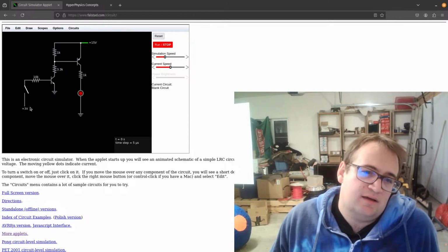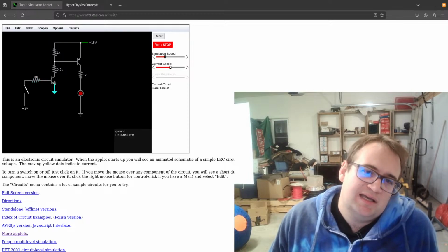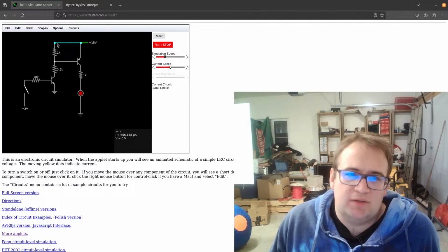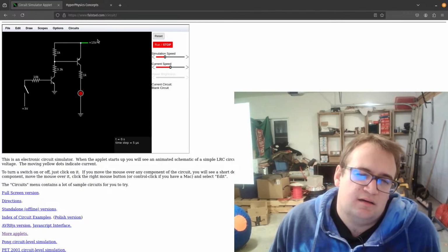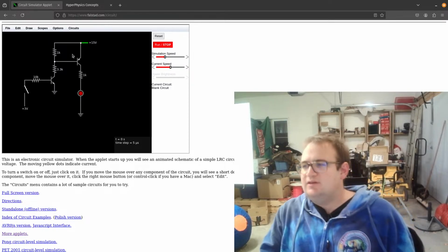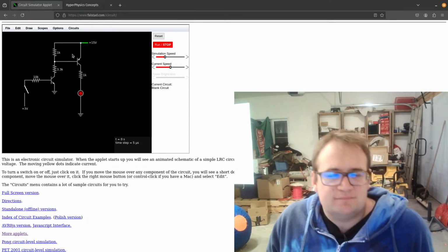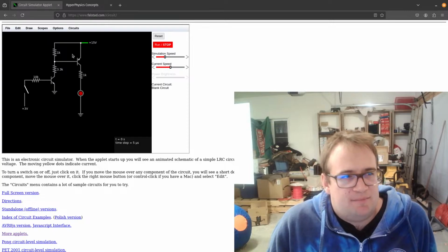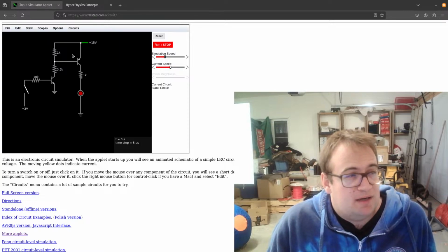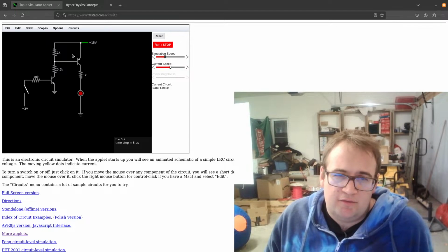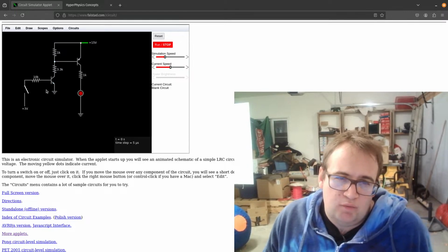So 0.3 milliamps going through. It will be trying to draw about 30 milliamps max through it. Now given we have 4.3 kiloohms there, 15 volts. These are bad choices for math, for in-the-head math. Let's just say it's 4, and that's 16 there. Then 16 divided by 4 is 4. And so just under 4 milliamps max would flow through there. So it's not going to be flowing the full, but there will be about that much.